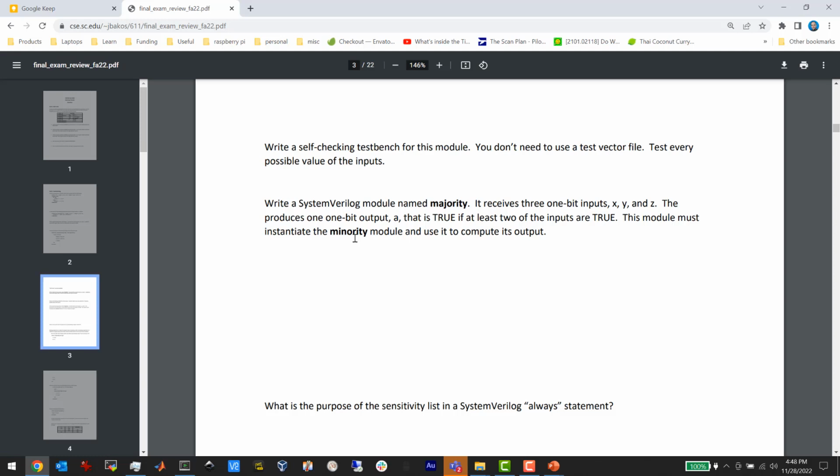That's an issue, right? Because of course, with the CPU, you could have a CSRRW instruction after every instruction to expose what you just calculated in each register, right? So you can have an add, CSRRW, subtract, CSRRW, and so on.